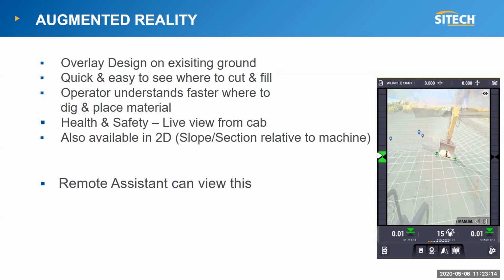But basically, for example, you want to cut the bottom of an embankment. So you can see on guidance the line, which indicates to me the bottom of that embankment. You select that line and the operator drives into that line and says, okay, I'm half a meter away, I'm 0.2 of a meter away, I'm on that line, and I can guide and cut out the bottom of that alignment. So that could be, say, bottom of cuttings, top of banks, center lines of roads, edge of your cut.